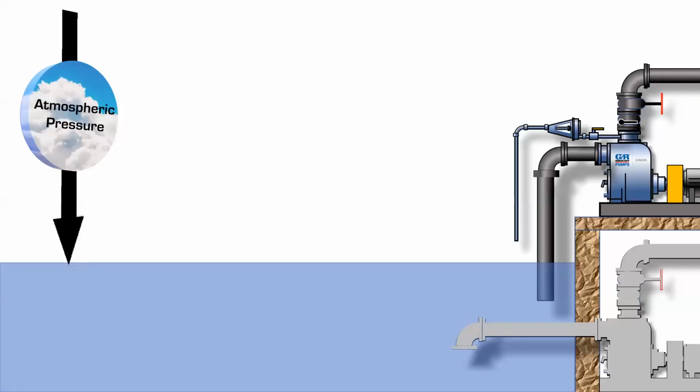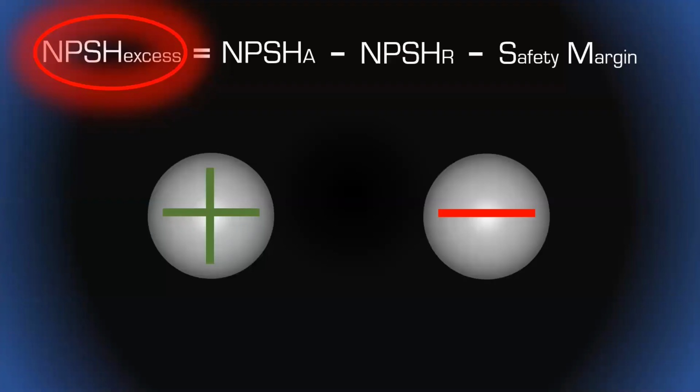So let's now go through that same calculation again, a little shorter this time. We're not going to go through each one. Hey, Steph, I think it could be worth answering this question. Go back one slide to the NPSH calculation. Yeah. And the question here: when calculating NPSH available, should we include the pipe exit into the pump, K equals 1, or is that included in the NPSH required? The pipe exit into the pump.